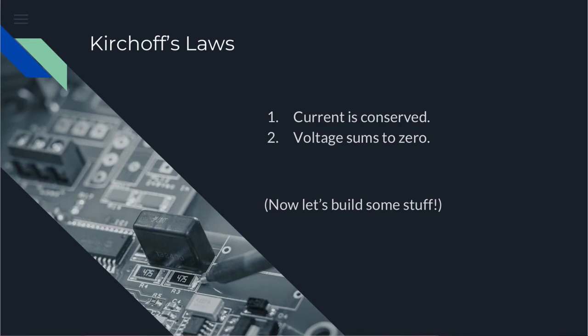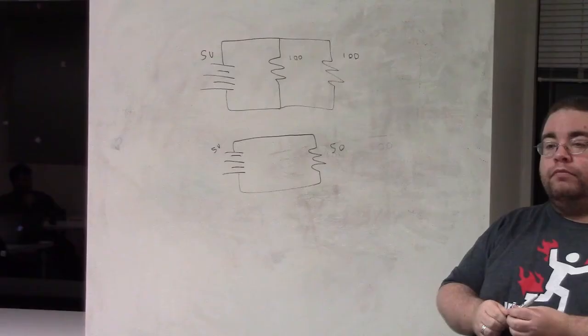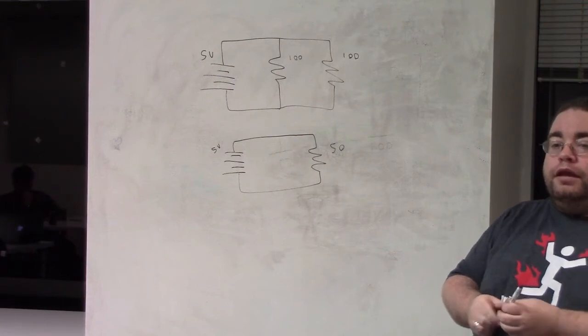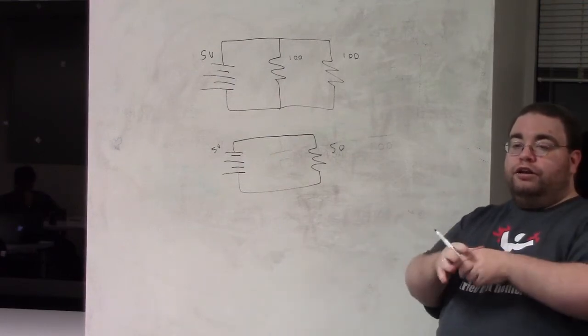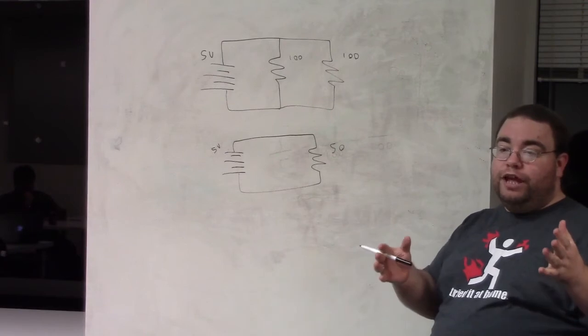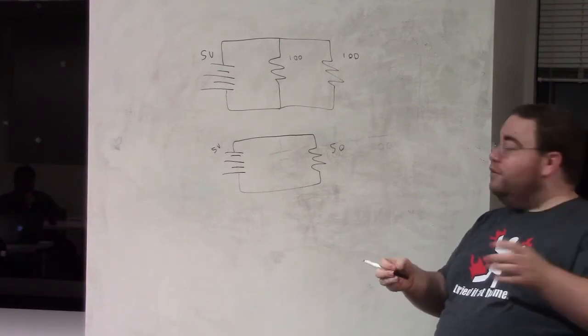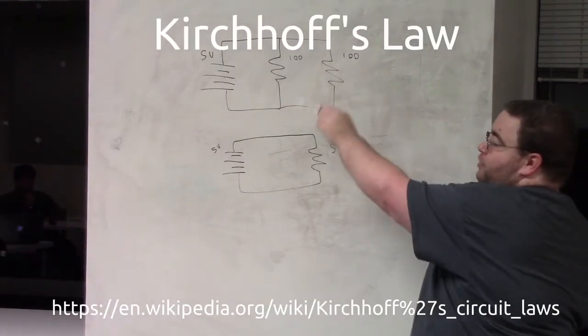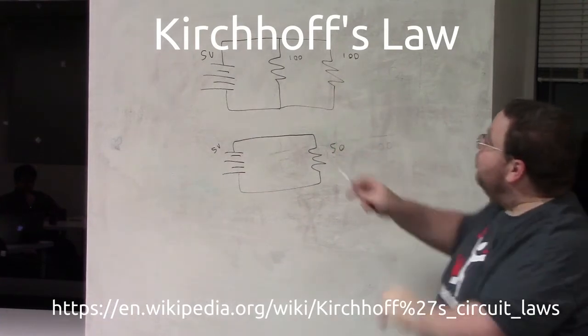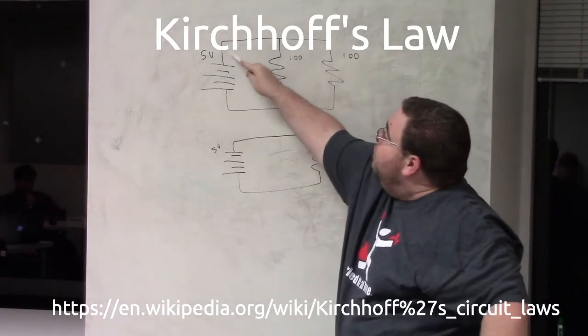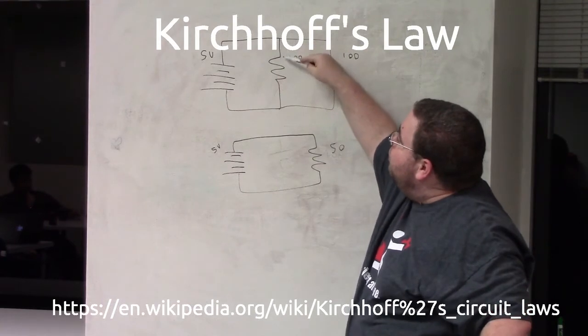Kirchhoff. You mentioned Kirchhoff earlier. Yeah, how in one node the current going in equals the sum of the currents coming out. Current is conserved, basically. You can't create or destroy current. There's going to be a constant amount of current going around this whole thing. So all the current that enters this node from this line is going to go out here and here.